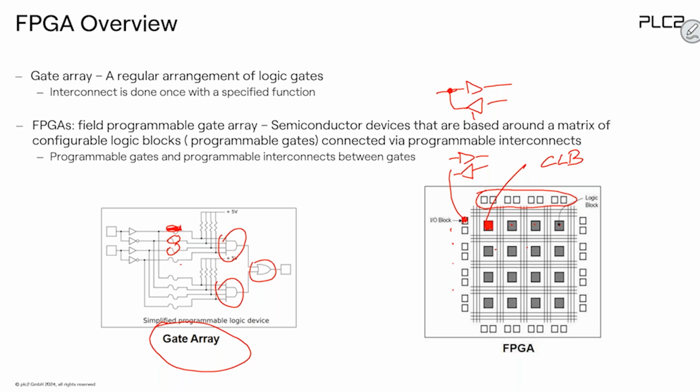And then, that is very important, we have a lot of routing channels. These are predefined, pre-built routing channels. They're already there, so during your design of the FPGA, you never build a routing channel or destroy one. These routing channels are basically multiplexer structures. By programming a multiplexer, you can select, let me zoom in here, a so-called switch matrix. This switch matrix might have channels horizontally and vertically. If you decide to use this routing line and you would like to switch to this one, you select the multiplexer and switch from this line to this line. These are switches, but you're not building the switches, they're already built. You're just selecting the switches.